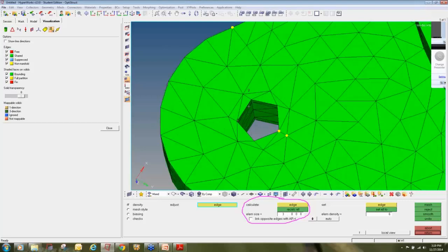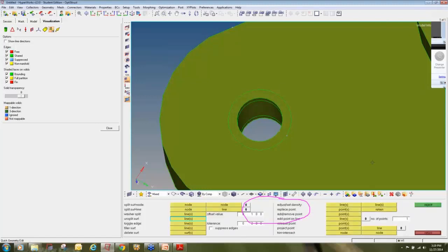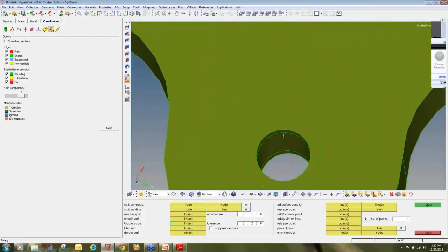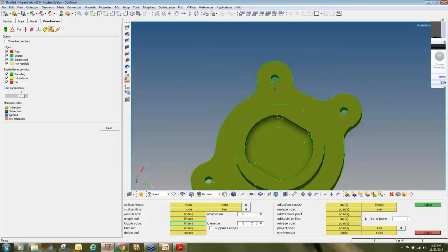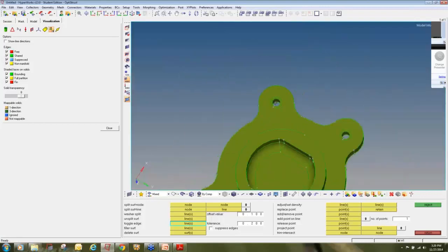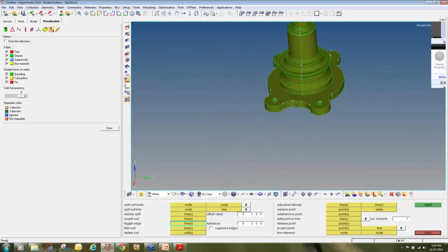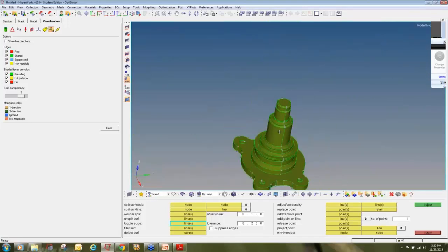And you can see there are different lines available. So what I will do, once the meshing is done, I will again go to quick edit panel on geometry page and unsplit some of the lines. So editing the geometry, if I edit the geometry, I will toggle these lines, will help me to do a better meshing. So geometry editing is very important part, and that helps you to create a better mesh surface. So those lines which you don't want, you can toggle it down.